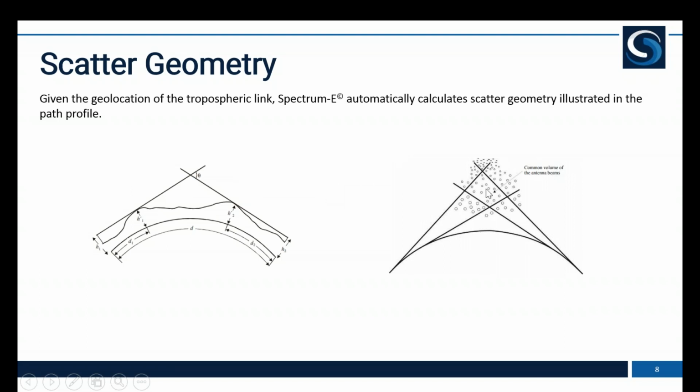And that is the region, this is where the most optimum reflection point of the troposphere is, at this scatter angle. However, it's not just a precise line. That's for drawing up the geometry on the left side. On the right side is what you actually experience in real life. So in real life, this scatter region is actually bigger and is more like a polygon, as you see here. And so this region is called the common volume.